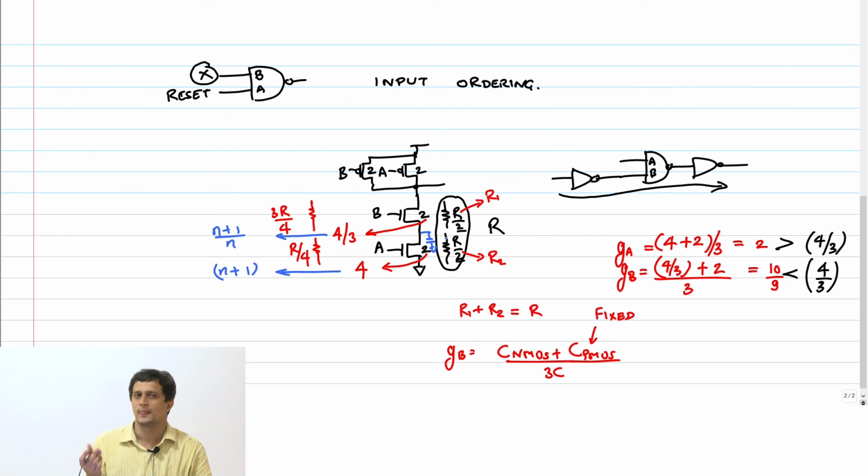And in fact, that in between capacitance here, you have to recalculate a little bit. It may not even be true that it's a shared uncontacted diffusion and stuff like that. So I would just say you have to rely on simulations on the RC extracted netlist. Okay?